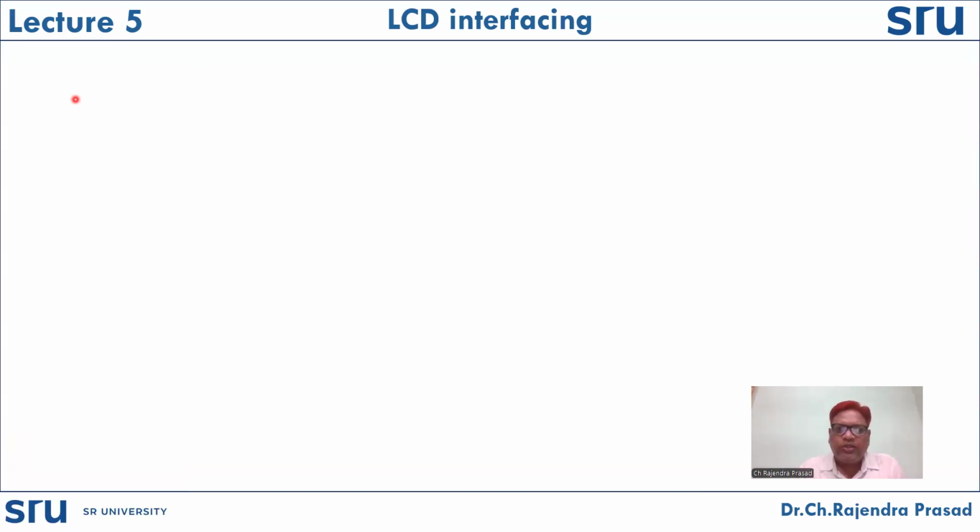So first I am using that library. When you are using a library, first you need to include it. Here I am including the library with the help of #include LiquidCrystal.h. And one more thing you need to remember: L and C should be capital for this library.